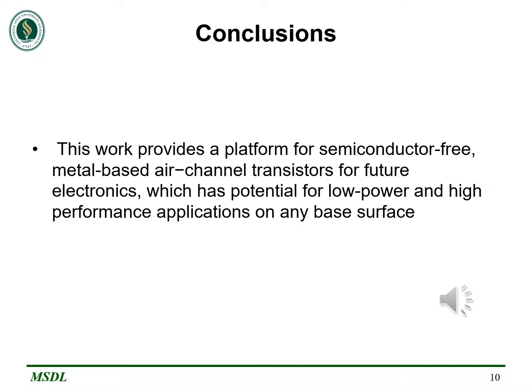All three metal-based air channel transistors behave as transistors with significantly lower emission current of a few tenths of nanoamps. All devices behave as bidirectional transistors due to the symmetric source-drain geometry. However, variation in the positive and negative bias operation is observed depending on the tunneling mechanism of electrons.